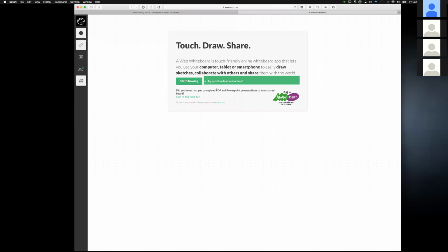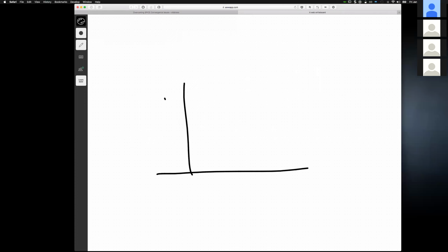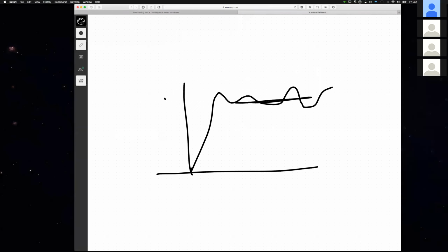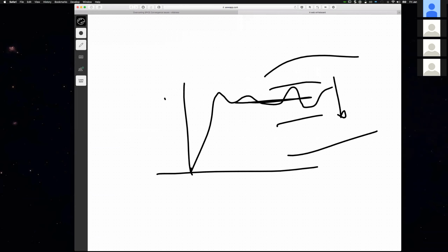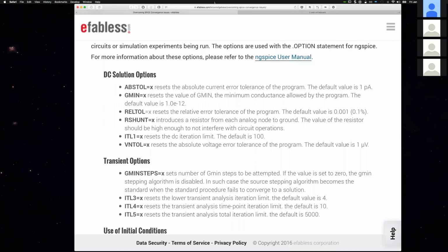It's all about mathematics. The mathematical iteration is leading you within a certain error margin. If you loosen the tolerance, you're increasing the range at which the solution can be found, which reduces your ability to get an accurate answer. All that is subject to the final value you're trying to solve for, and the accuracy of that value, what resolution, what number you want to see.